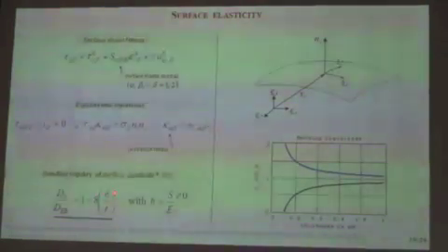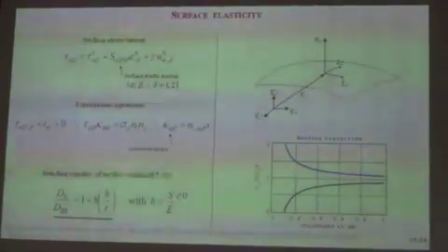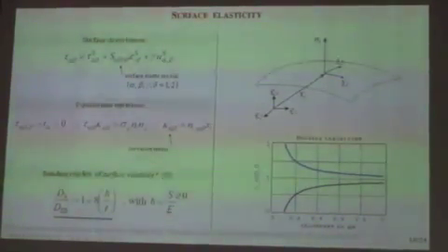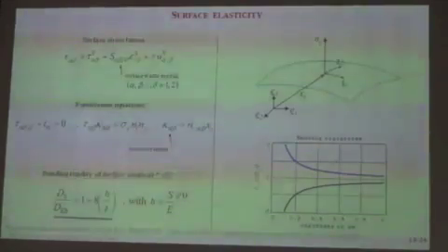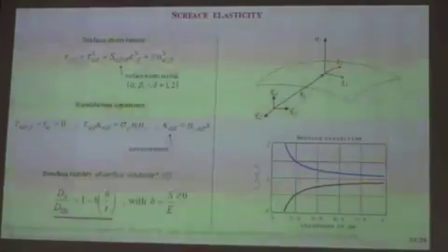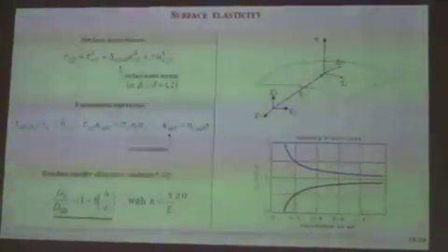And the somehow material length scale parameter one can identify here depends on the surface elastic moduli and on the Young's modulus of the bulk material. And interestingly, the surface elastic moduli can also be set to negative values. And negative values somehow will mean a softer elastic response in the small scale that is also observed in some experiments.